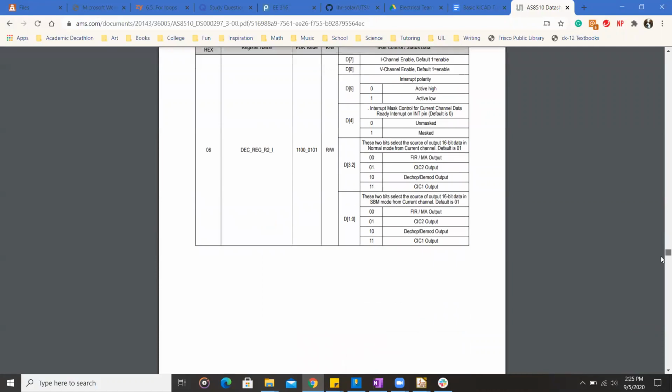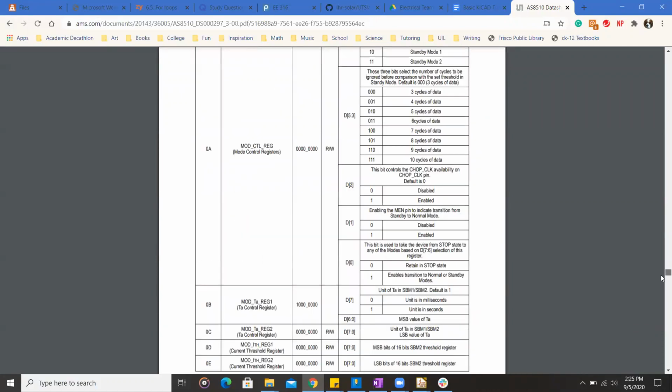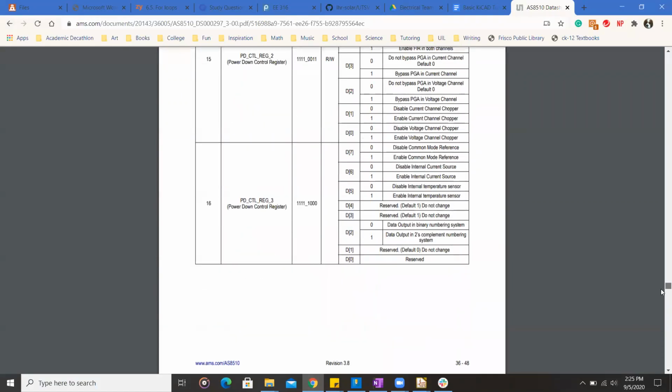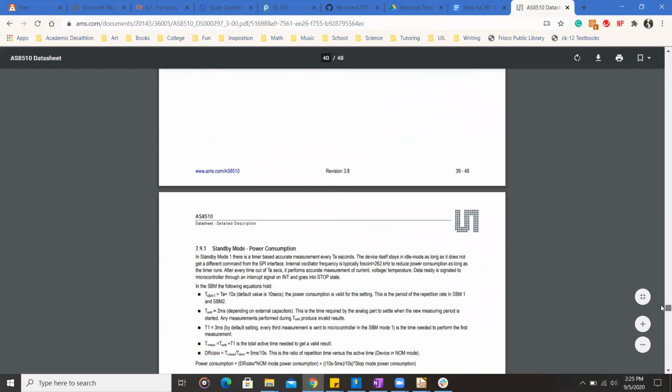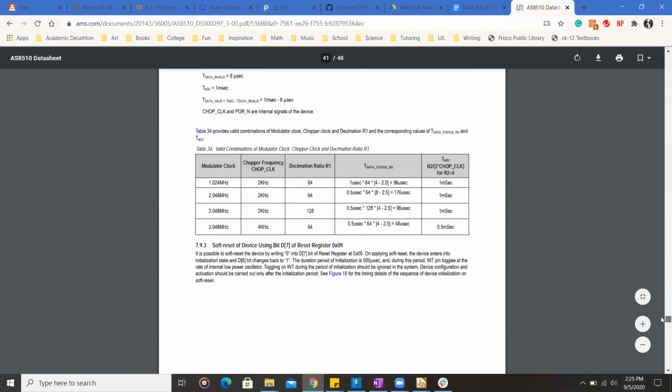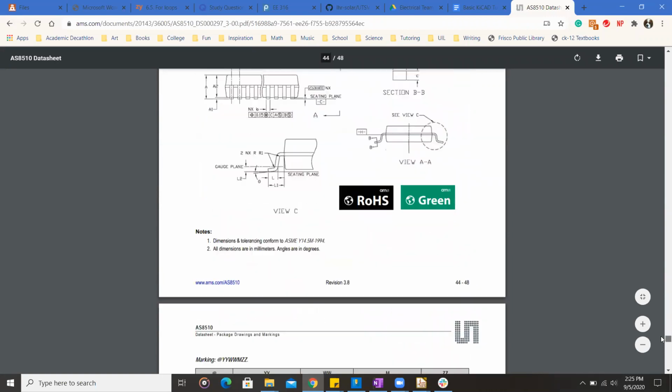For the footprint, what you want to pay attention to is making sure you have the dimensions correct. You want to make sure that its size is correct and the size of all its copper pads are correct, because if it's not, then you may not be able to fit the component there, or the footprint that you make might be too big or too small, or it may not have a correct connection in the right place. So double check and make sure that all the measurements are correct.